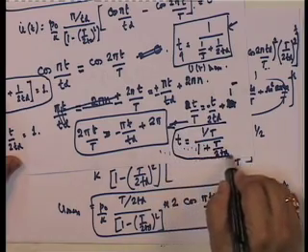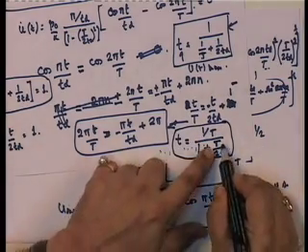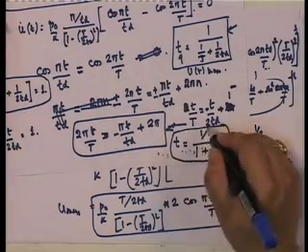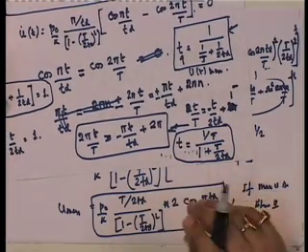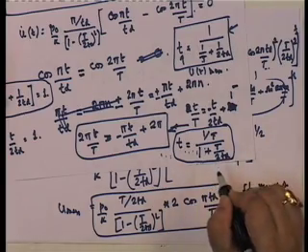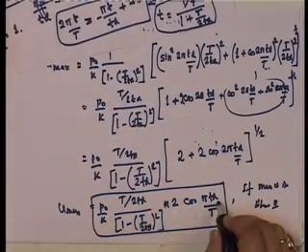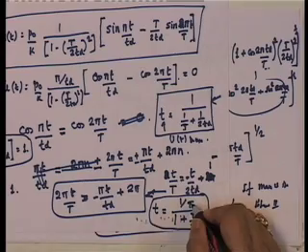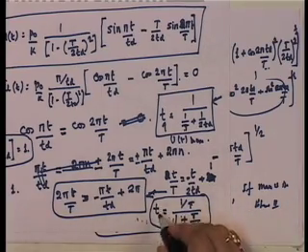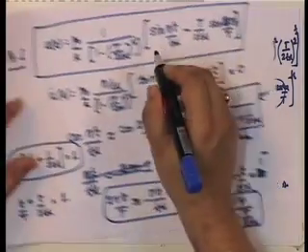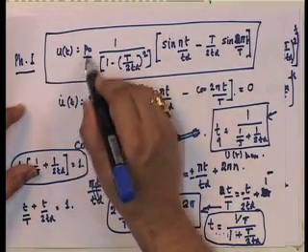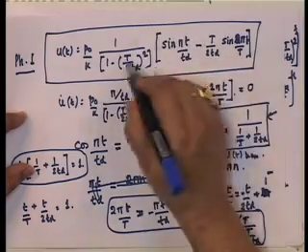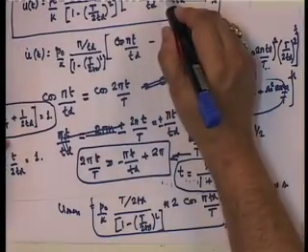Note that this time duration does not only depend upon Td by T, it also depends on T itself. Therefore, this max will occur at different times for different Tds. So all you need to do is find this for a given Td by T, and of course, time, you get this T, and for that T substitute into this and get the dynamic amplification, which is u max upon P naught, and compare this value with that value.